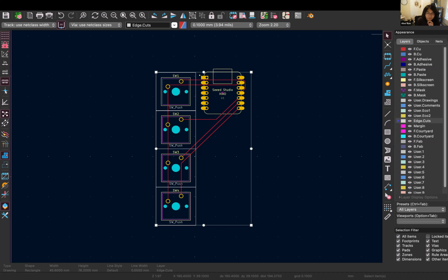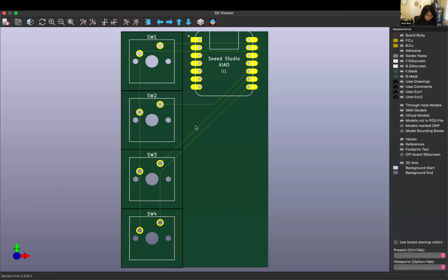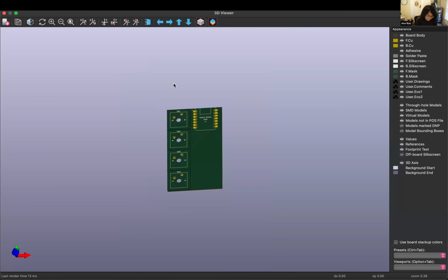We're making the grid. So we're making the outlines, because right now in our schematic, we only have a bunch of floating parts. We need to define an actual board for it to sit on. All I did was go to this Edge.Cuts layer right here, and then I drew a rectangle. And what that lets us do is, ta-da, in our 3D viewer, we have a board.